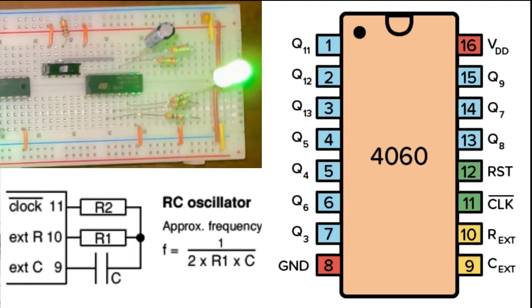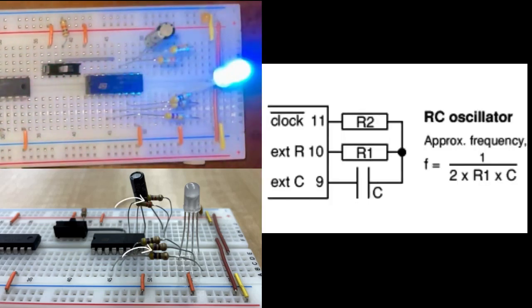This circuit uses the 4060's internal frequency division capabilities to create an oscillator. The 4060 IC is a 14-stage binary ripple counter and oscillator where an external capacitor and resistor determine the oscillation frequency, and its cascaded stages divide the internal clock signal to produce various output frequencies. The external analog components shape the timing characteristics of the oscillator.